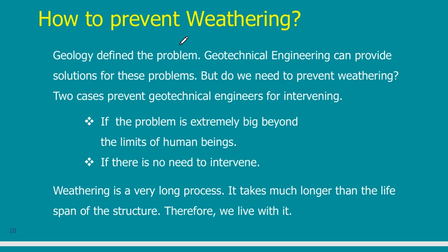Because for rock to weather, it would take millions of years, or 5,000 years. My building is not going to last more than 100 years. So why would I prevent weathering? If somebody asks you, did you take weathering into consideration in your design, it means that he does not understand geology. He just knows that there is something called weathering. But weathering takes a very long time. So I don't want to prevent weathering.